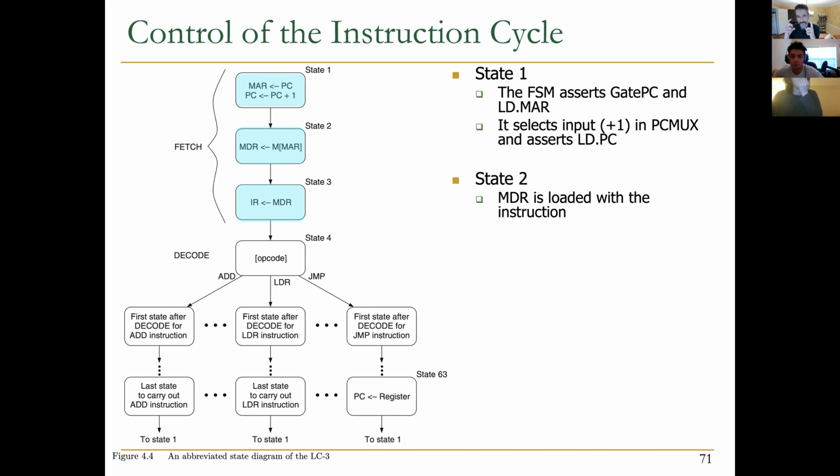So this is the 3-step, which here we model in the finite state machine only from the fetch stage of the instruction cycle. And you know that the next stage would be decoding. So once you have the content of the instruction in the IR, you need to decode it. What's the particular instruction you want to execute? So you need the opcode. From the opcode, you can decode what's the instruction.